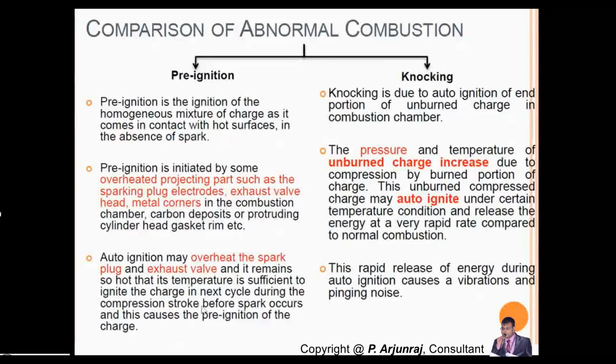Even the auto ignition or self ignition may also overheat the spark plug, and the exhaust valve will remain at the hottest temperature, and that will self ignite and create a phenomenon called pre-ignition.